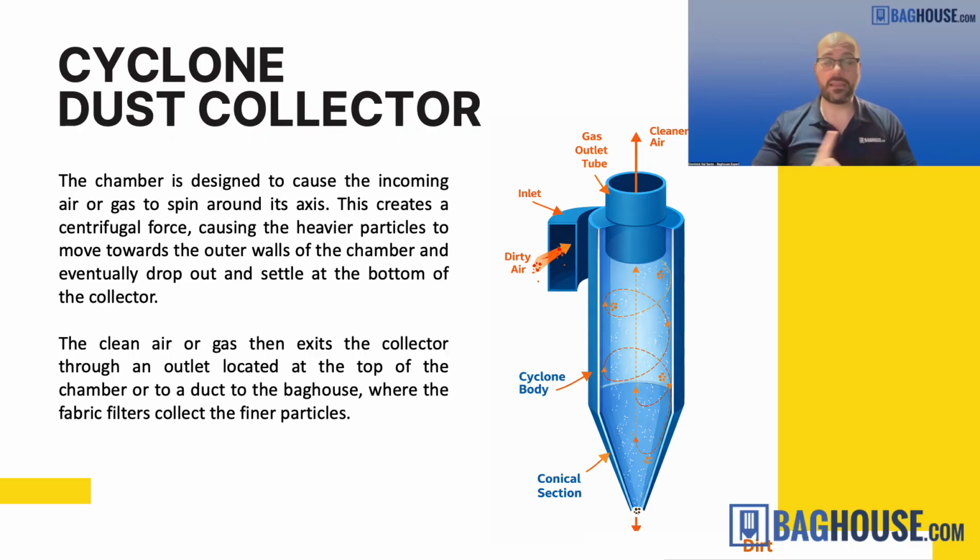Cyclones work by the air coming in and spinning around really fast, and it removes a lot of the dust particles from the air without any kind of filters. Now, the problem with cyclones is that they cannot remove the absolute finest small dust. Because they can't get rid of the really fine dust, a little bit makes it out the exhaust.